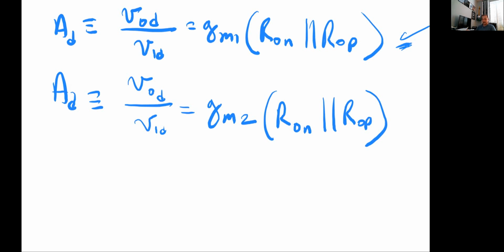So that is a very nice attribute of differential signaling in general, okay? So that's why you see that high speed signaling is done differentially. Because if you have good common mode rejection, then your common mode noise is not going to affect and degrade the signaling.